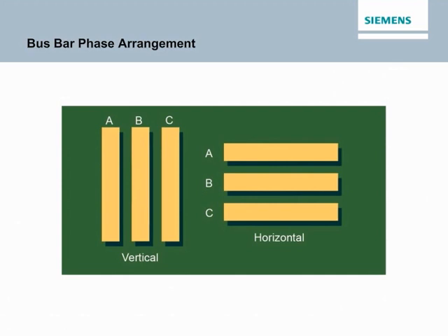The NEC requires bus bars to be located so that they are free from physical damage and held firmly in place. Bus bars are required to have phases in sequence, so an installer will find the same fixed phase arrangement in each termination point in any switchboard. This requirement is established by NEMA, the National Electrical Manufacturers Association.